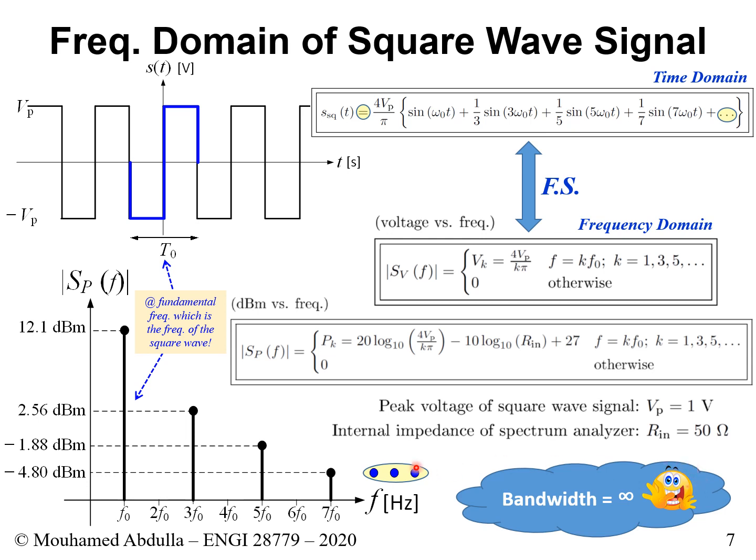So how do we ensure that this achieves a finite bandwidth? Well, one approach would be, like we said, to not go until infinity, to stop at a specific large n. Remember we said this large n? Large n is the highest value for the harmonics, right? So we stop at some value of the largest harmonic. Maybe we could say that this square waveform, I could approximate it with, I don't know, maybe 5 harmonics, until the 5th harmonic.